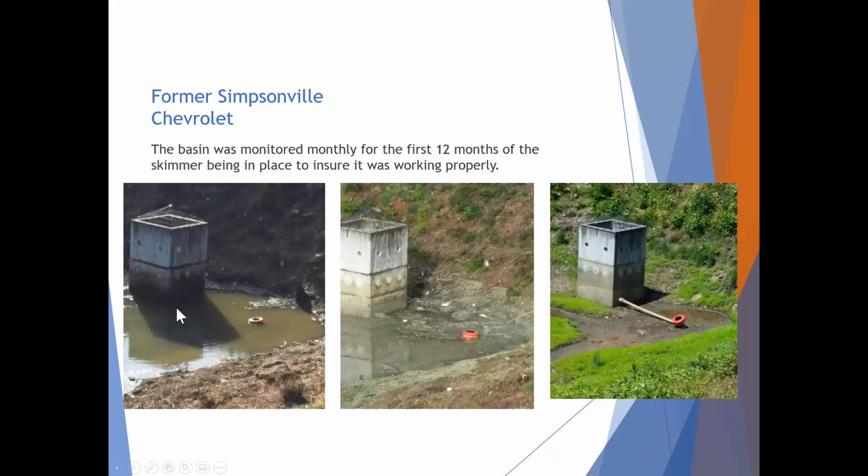And when we did that cleanup, we found that the bottom of the pond had about 6 feet of muck in it. If you look at these pictures where you can see the lighter circles, hopefully you can see that on your screen, that's the old outlet. And it had a 2-inch orifice 6 feet below this muck. So 6 feet down was there. And so we worked with the county and with the client and redesigned this pond.